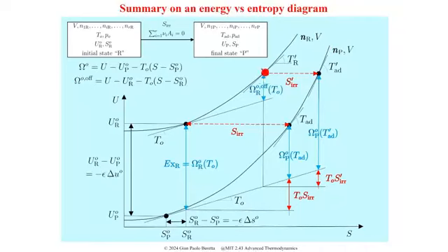So if we could have the combustion occur by preheating our reactants at a higher temperature, for example, T1R here, when I do the oxidation, the adiabatic flame, I produce less entropy by irreversibility, and therefore I consume less exergy. That increases the efficiency. So preheating the reactants is a way to improve the efficiency.